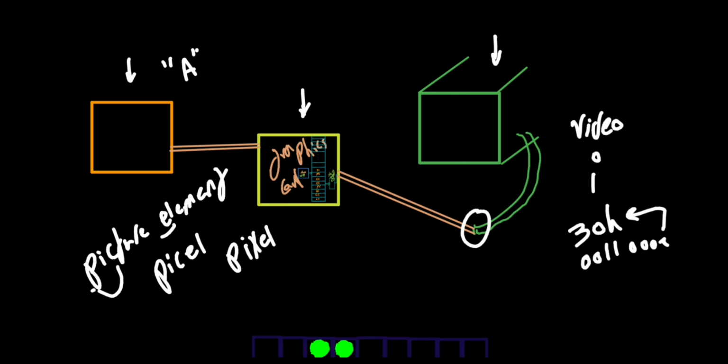The first thing that the graphics card would do is feed this to the monitor on the VDO pin. First, 0 would be given to the VDO pin. Obviously, 0 would cause the background color to be shown, or no light, therefore the result would be black. Therefore, black would be shown on the first square.